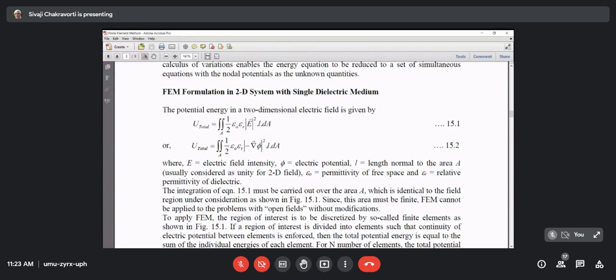Whereas for half CV square, we have to know first the potential difference, but that involves at least 2 points, and we have to know C for a given configuration. Whereas for half epsilon E square, we just have to know the material property, which must be known, and E can be defined at a single point because E is always defined at one point.